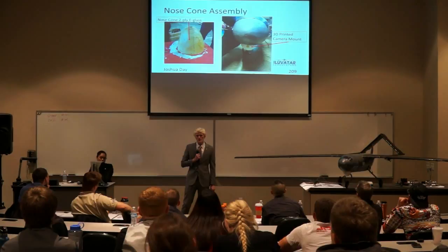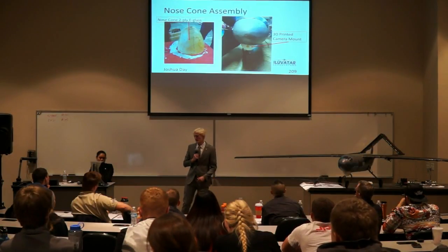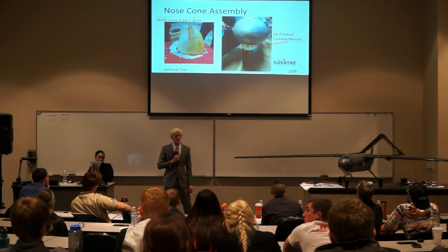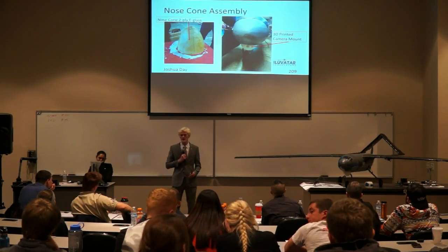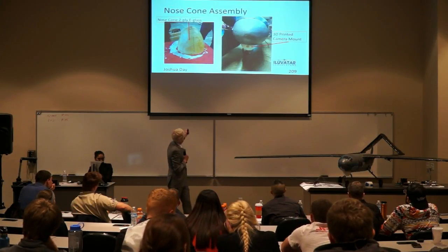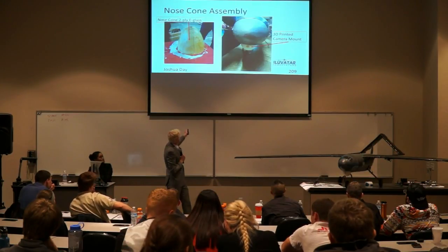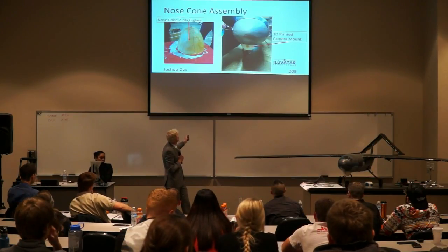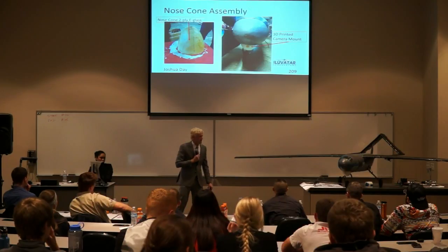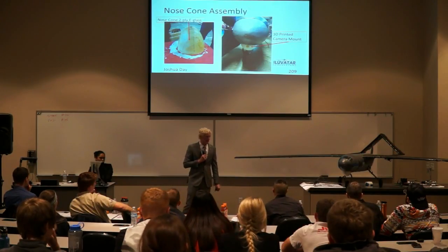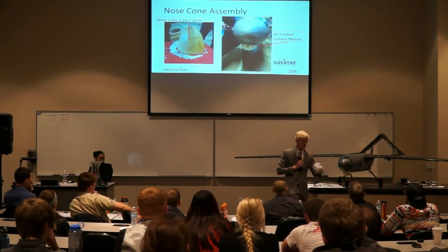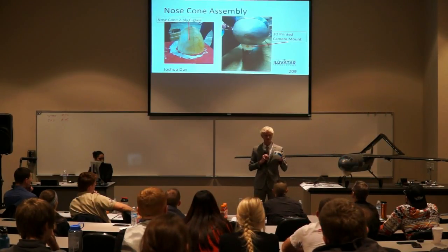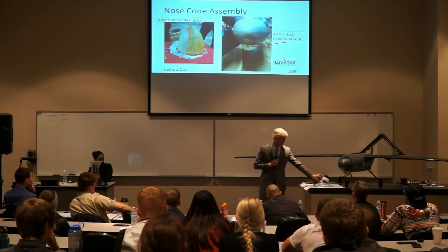To make our nose cone, we created a foam mold and then put a 2-ply e-glass over that. And then we carved out a section of the skin and the foam in order to put the camera mount inside. The camera mount is 3D printed and it detaches. Here's one of our older ones that we used during flight test, and it detaches, and there's a pin location so that it won't come out during flight.